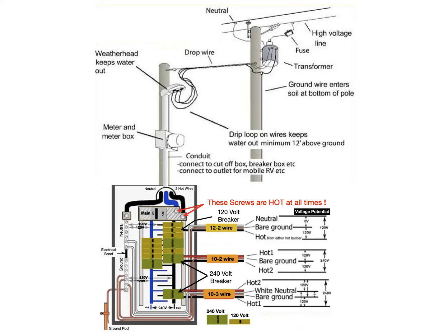The overhead power connection from the utility lines to the service entrance is referred to as the service drop. It has 3 wires: 1 neutral line and 2 hot lines. The hot lines maintain a certain potential, like 120 volts, compared to the neutral line. There are 2 types of service drops, a mast service drop, and an underground service connection.